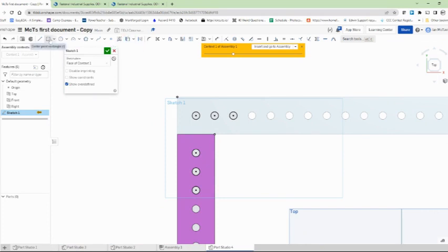And I'm just going to do a little rectangle. So I'm going to use that point. I'm going to hold my mouse over it, click once. Whoops. Turn it off. I don't want a center point. I want a corner rectangle, G. So hold my mouse over it, click, that becomes a corner. That's more like it.